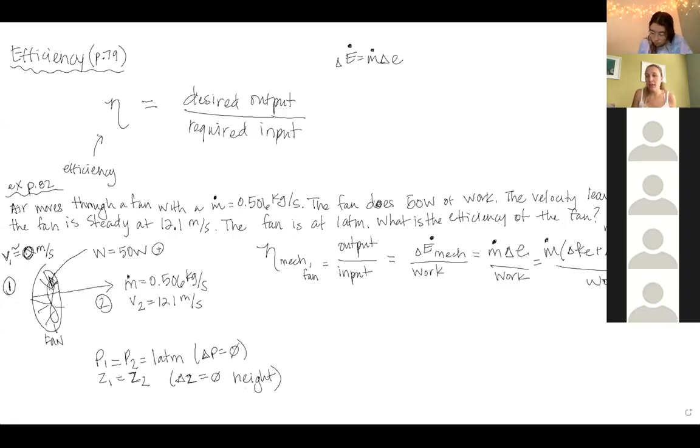Yeah, Elizabeth. So we can cancel internal energy. There's probably a little bit of internal energy changing when we're speeding up and putting it through the fan, maybe cooling it off a little bit, but the change overall here is going to be negligible. We're going to ignore any internal energy change. So we're going to say change is very small, about 0.